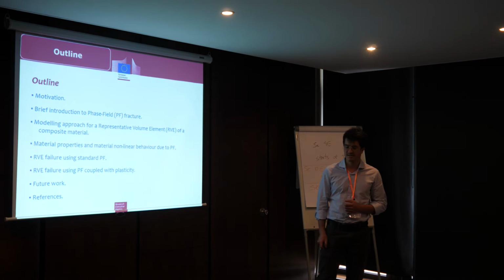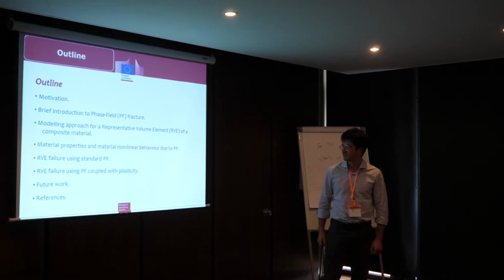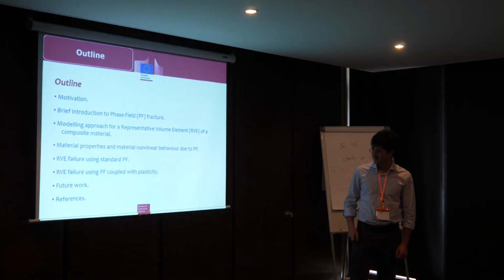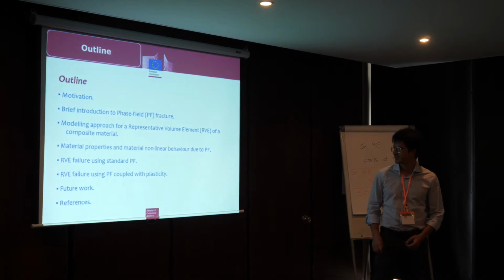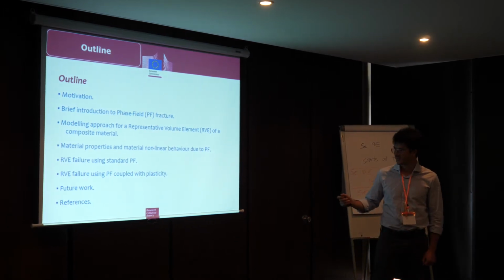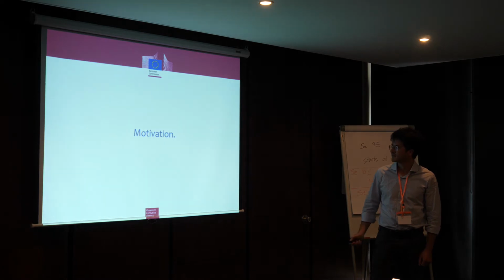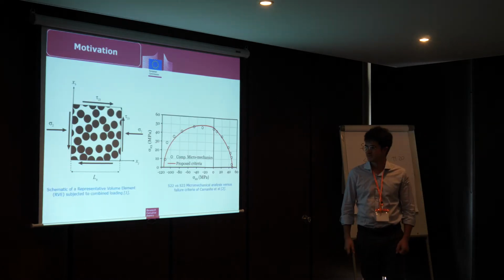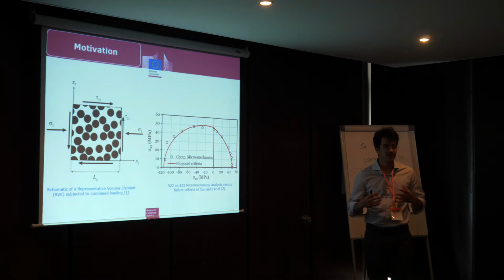Then I will explain what is the modeling approach when it comes to representative volume elements in composite materials. Then I will move to the analysis of the properties and what is assumed when you use phase field for fracture. Then some results when it comes to RVE analysis using the standard and the phase field coupled with plasticity, and some future work. So the main motivation to use RVEs is that we can apply very different load combinations.